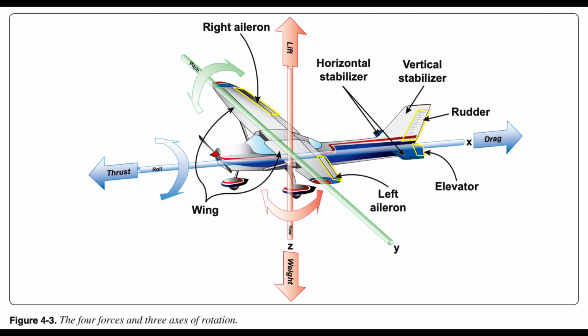Form drag. Form drag is the drag created because of the shape of a component or the aircraft. If one were to place a circular disc in an airstream, the pressure on both the top and bottom would be equal. However, the airflow starts to break down as the air flows around the back of the disc. This creates turbulence and hence a lower pressure results. Because the total pressure is affected by this reduced pressure, it creates a drag. Newer aircraft are generally made with consideration to this by fairing parts along the fuselage teardrop so that turbulence and